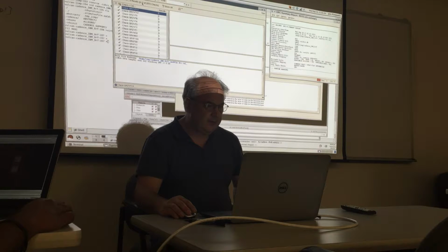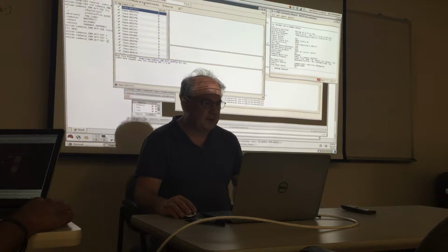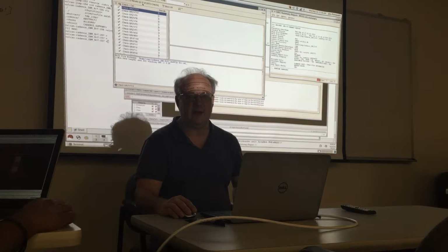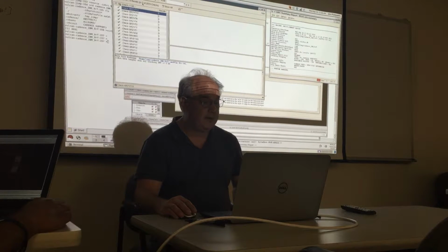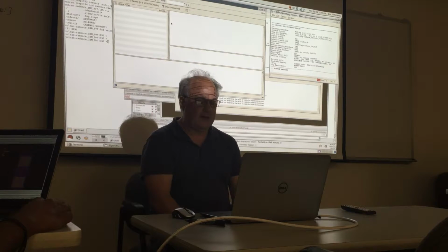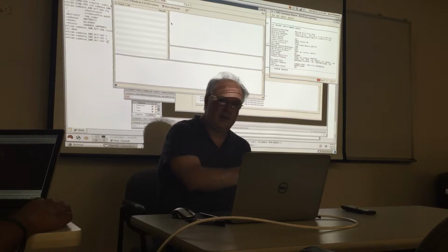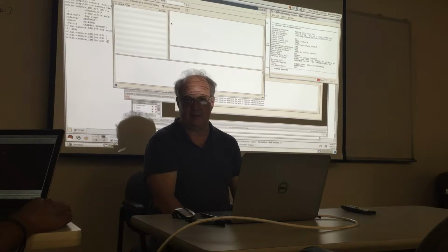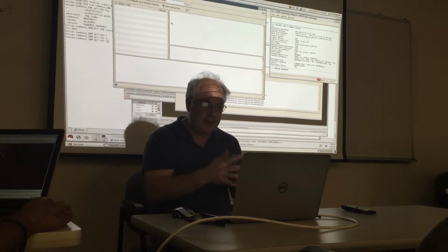If you don't have any problems, the easiest way to decide that is just to look for the 0. So if this is marked with something other than 0, then you have a DRC violation. And you're like, well, where the heck is it? Well, it's in this list somewhere. And the easiest way to get to the problem is to just show unresolved. And since we don't have any DRC violations here, nothing shows up. But if you did have one, then you would have that listed along with a red X. Okay, and then you'd have to look at that.